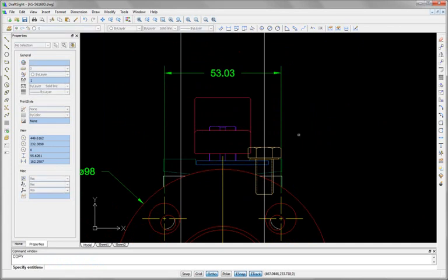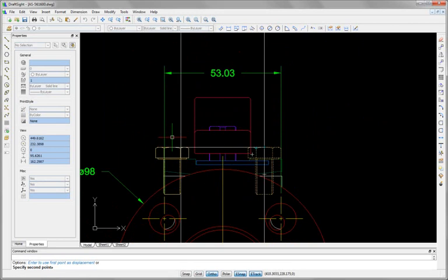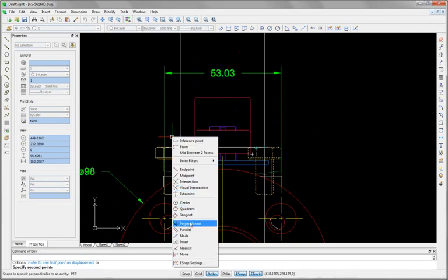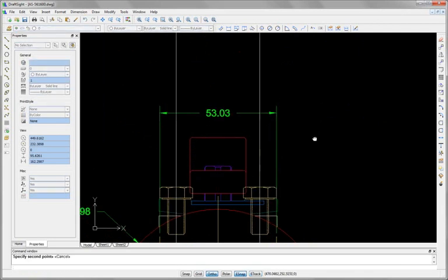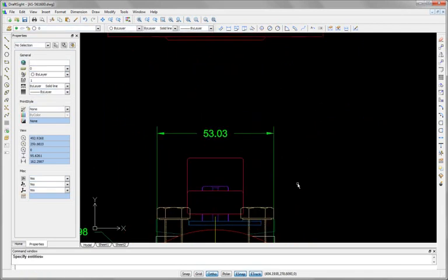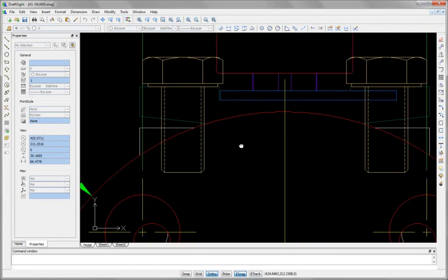I can copy my previous components like before, and to make sure I have the appropriate location, again, I'm going to use a specific snap, in this case perpendicular to that infinite line. I'm done with the infinite line and I can delete that, and I want to do some trimming here.